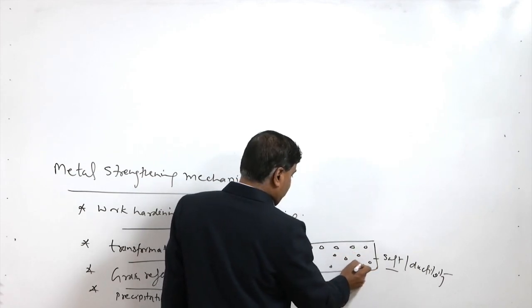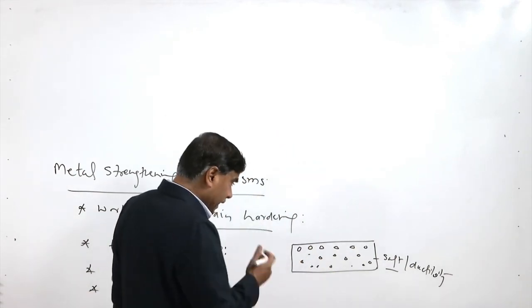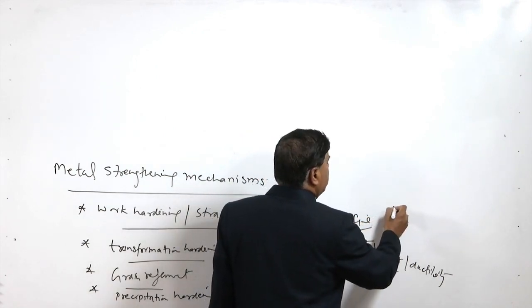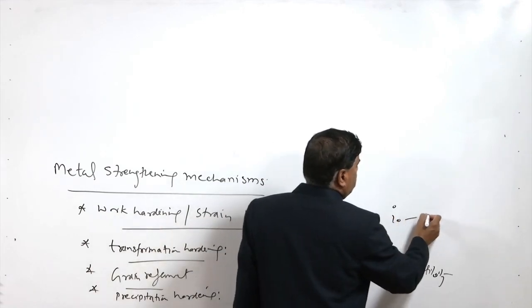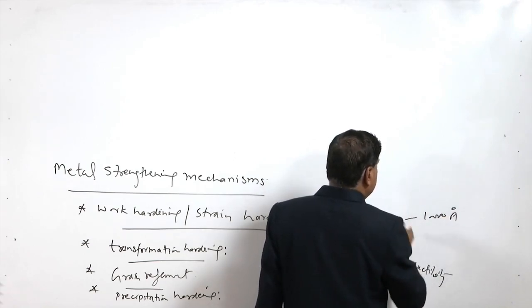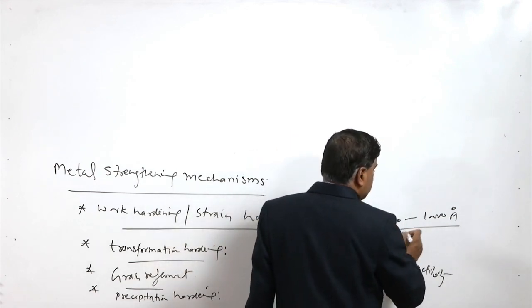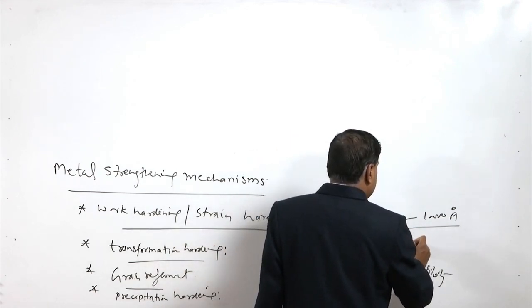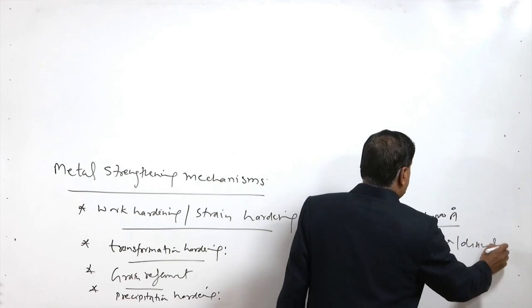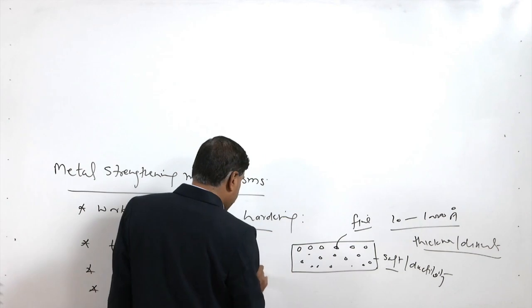So, precipitates like say in most of the non-ferrous metals, these precipitates in controlled way are developed so that they can offer the improved mechanical properties. So, these precipitates are actually very fine in size, maybe like say 10 to 10,000 angstrom, and this is say maybe thickness and similarly the diameter. So, thickness as well as the diameter, it is very fine and very thin. So, under the effect of heat these tend to get dissolved.